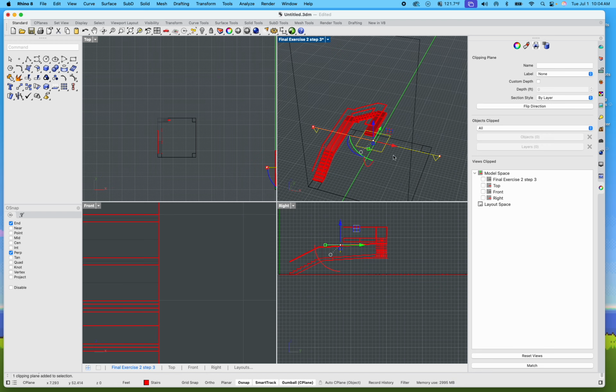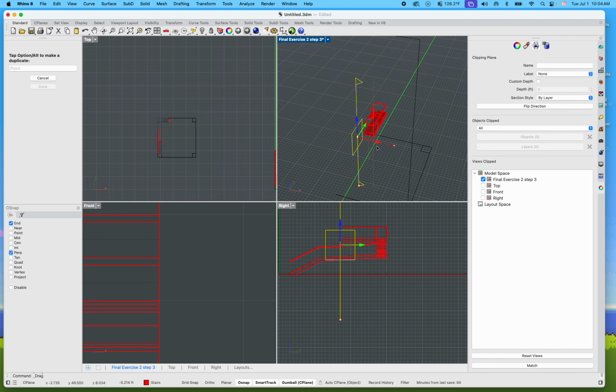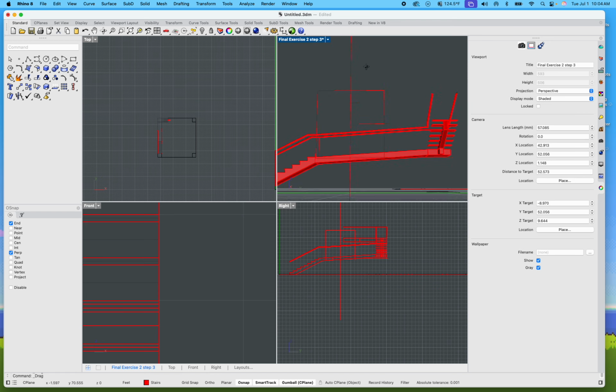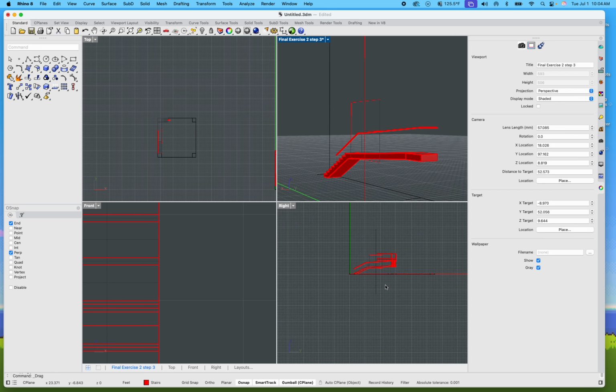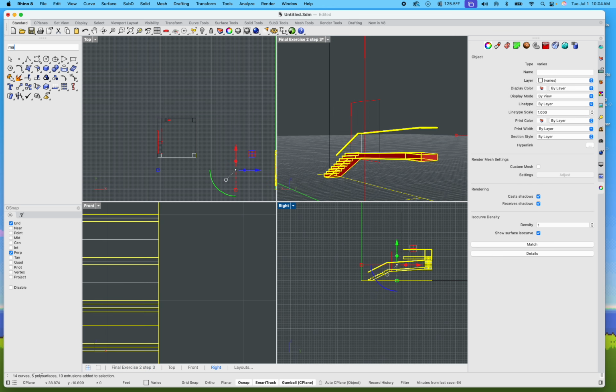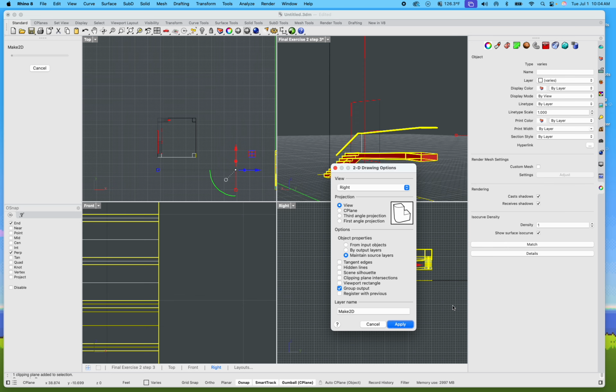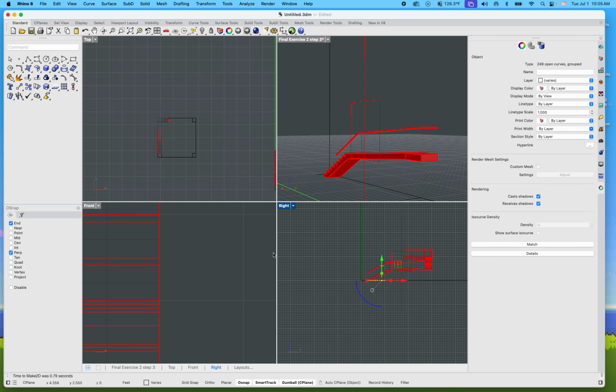What's nice also about the clipping plane is I can rotate it and I can make a section. Or maybe I want the other way. And I can get the section cut of that as well. Bam. I can take that section cut and make 2D and make a section. Now, obviously, I'm just asking for 3 floor plans, so not a big deal there. Really just trying to see what slices you want to take, right? And how you end up post-shading them is based on maybe what you've learned in Graphics 1 or Graphics 2.